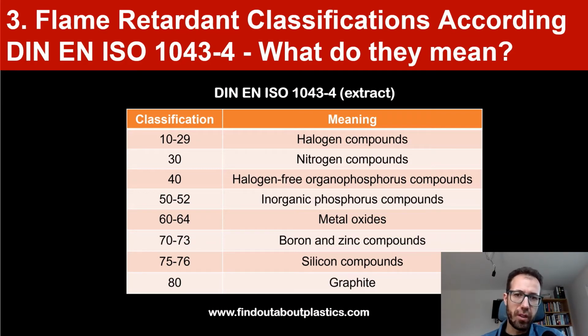So the halogen-free organophosphorus compounds, so organic system, because such flame retardants do not create electrical corrosion on your part, which in turn can result then in a short circuit of the whole system. And when you think of market segments such as automotive, more and more flame retardant materials in combination with other properties like thermal conductivity and electrical insulation are used.